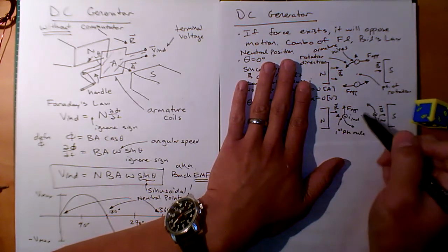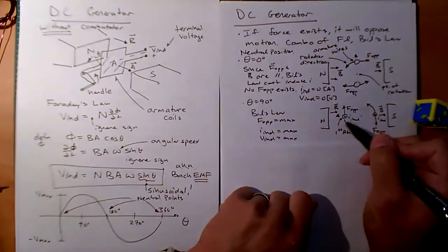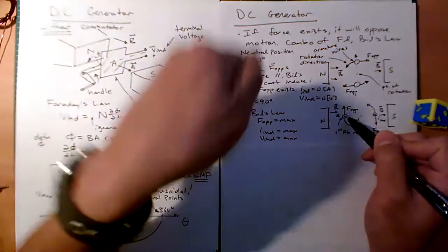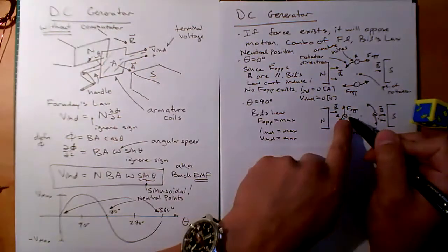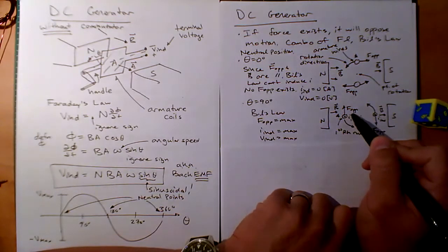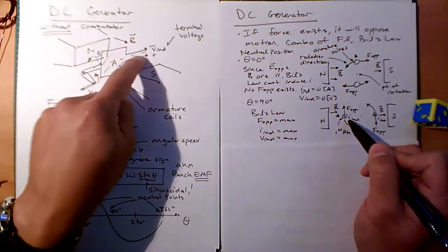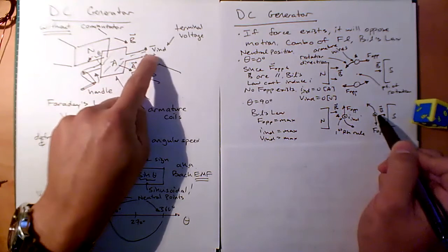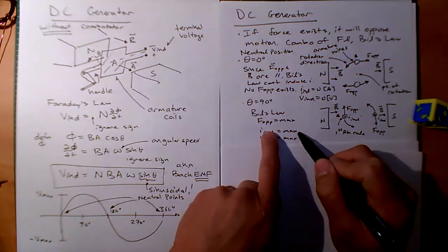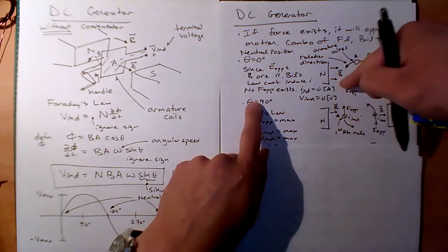And so in this orientation, remember I'm spinning this through, but if I just freeze frame right here, this is the orientation in this region where I'm going to get the most feeling of force resistance, like, oh, okay, I feel a little bit of resistance there, and I'm going to generate the most voltage here, okay? And so you can see that this current is actually coming up towards me, so it's going this way, right? And it's going down and into that positive terminal, generating a positive voltage, okay? So this is where I'm going to get the max voltage and the max current and the max force opposed, all right? And this is at that angle where the area is this way, okay, good.